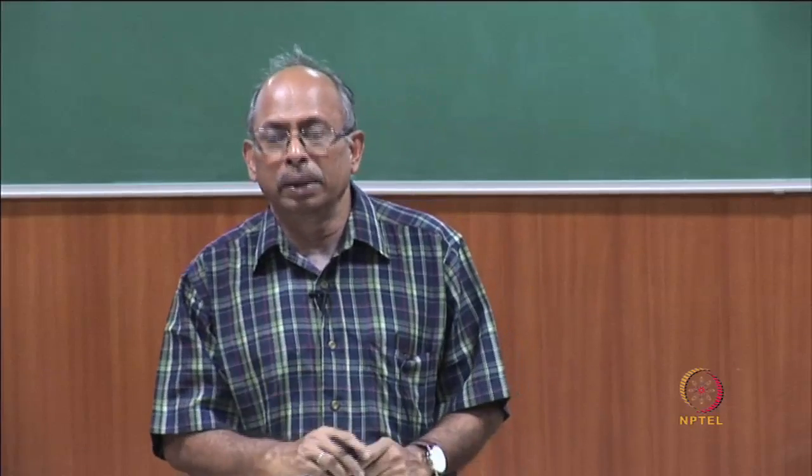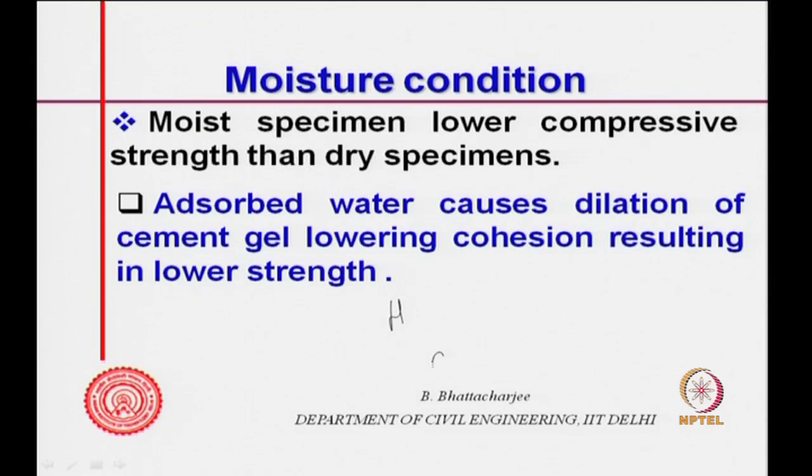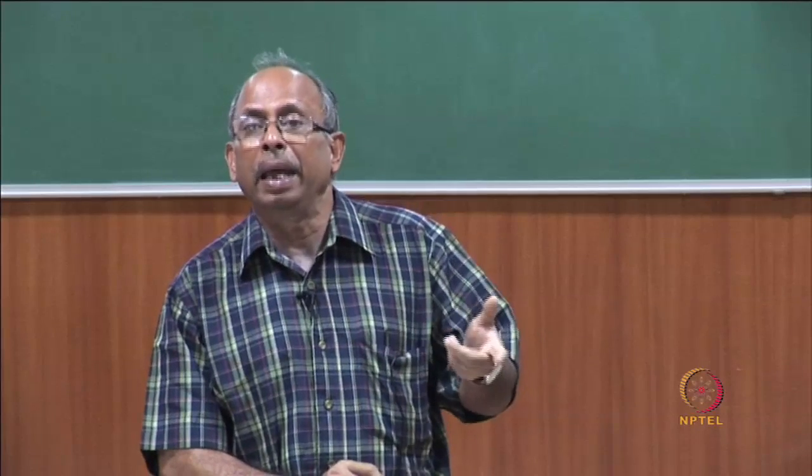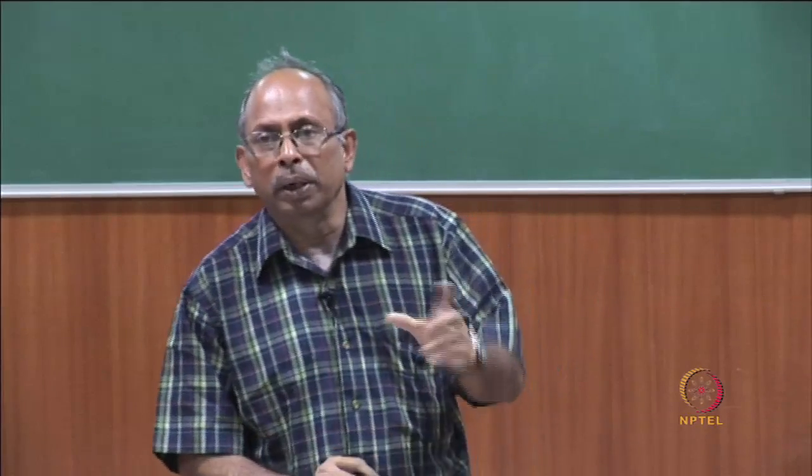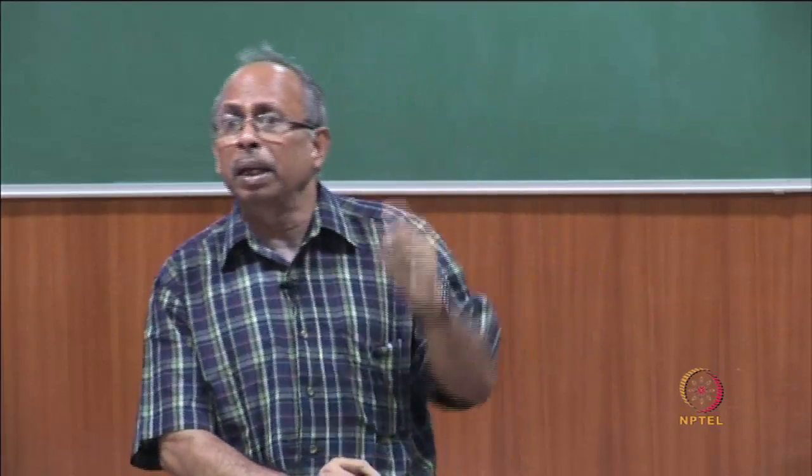As you know, water is a dipole, H-O-H. The center of positive charge is here, the negative charge is here. This is 105 degrees or some such angle, whatever the angle is. So, this is surely not 180. Therefore, it can form a dipole, and this water can get attached to charged solid surfaces in the case of very fine particles like clay or cement hydrate gel. They are adsorbed waters. We talked of this sometime earlier, right in the beginning.